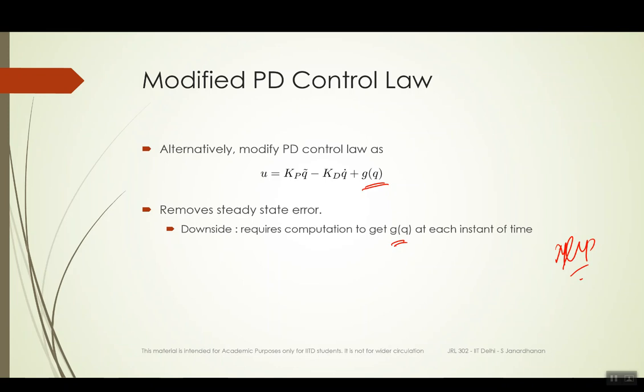Okay, so this is like the computed torque control. But the advantage over that control is, in the computed torque control you had to compute the Coriolis term itself for the compensation. Here we have proved that in the multivariable case, merely having kp greater than 0 and kd greater than 0, or kp and kd being positive definite, is enough for compensation, as long as the gravity term is not too large.